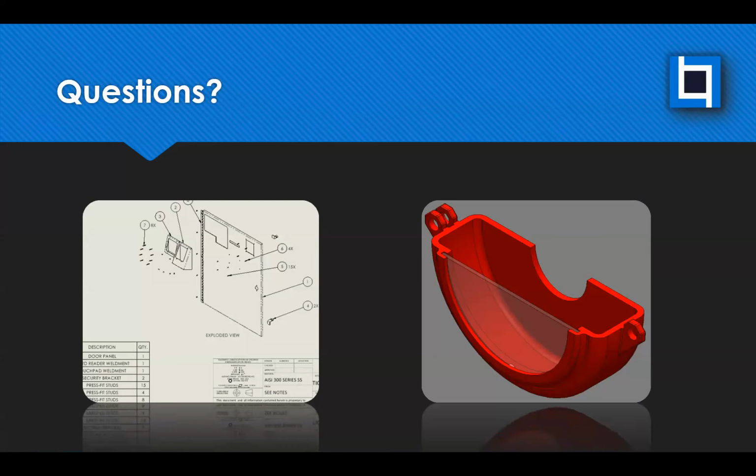Why did you decide to make this a multi-body part rather than an assembly? As far as that sheet metal, oh, that, because those two are the only custom parts. The assembled unit is really just that bolted onto it, it's just some hardware basically, and it didn't really make sense. The hardware isn't permanently attached. It's just some bolts that float in space. So it didn't really make sense to make it a multi-body in that case, from my perspective.